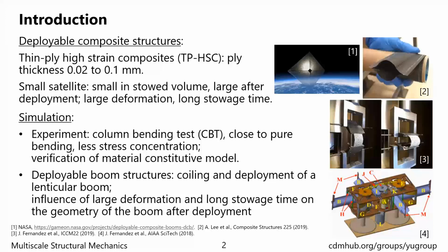Then, we can also do a simulation of a deployable boom structure. This structure contains a lenticular boom and a hub, and we can simulate the coiling and deployment of the boom so that the influence of large deformation and long storage time can be analyzed.